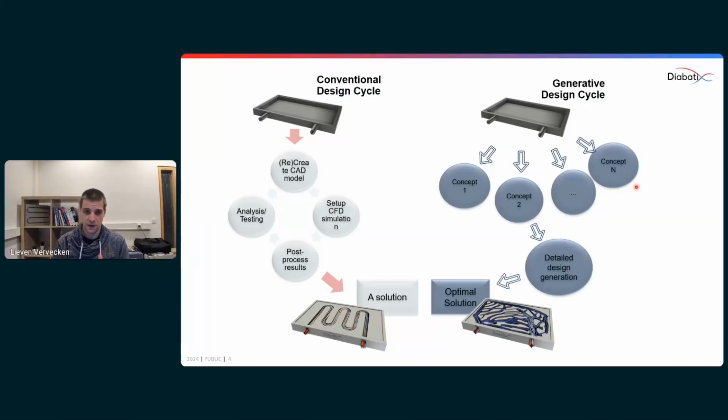things. For example, can aluminum be used, or can copper be used? Copper, of course, has a much higher conductivity, and thus will inevitably result in a better thermal performance. But copper is much more expensive and weighs more compared to aluminum. In the concept phase, you can try and figure out, is copper worthwhile? Is the improvement, relatively speaking, worthwhile over cheaper materials like aluminum?